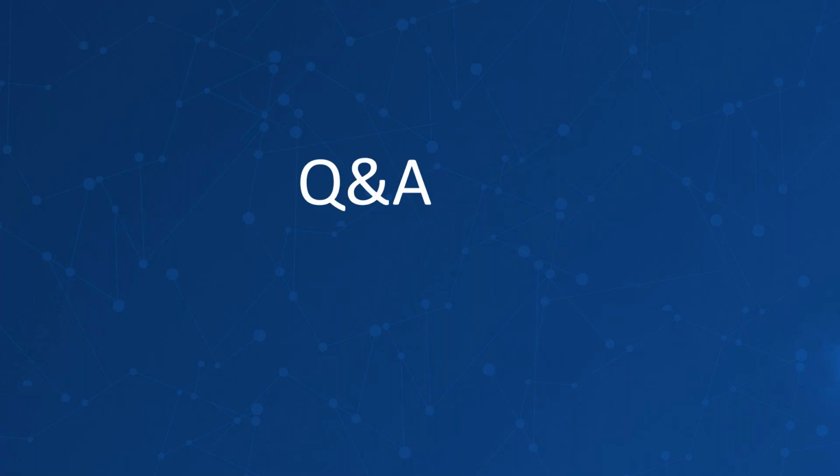Yes, Steve. Yeah, thanks. We have a couple of questions at different levels, so let's try to take them. And of course, if you can't really respond to one, maybe do a one-to-one response if you need to do some kind of further investigation. The first question is, can you use ISO 19650 revision sequences like P01, P02, etc.? Because you showed in the Vault area revision sequences A, B, C. Yeah, absolutely. So those are configurable. So if I want to have 1.1, 1.2, 8.1, 8.2, that's all possible. Yes, absolutely.